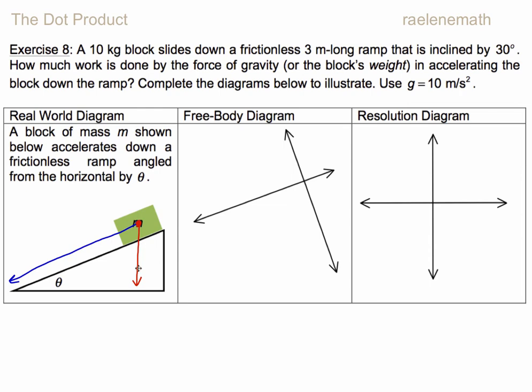So we can put the force vector over here in the free body diagram. And we don't necessarily put the displacement vector here because free body diagrams are for forces. What we do need to do is to resolve that force vector that we've just drawn into its horizontal and vertical components. So I will copy that vector, place it over here in this rotated axis.